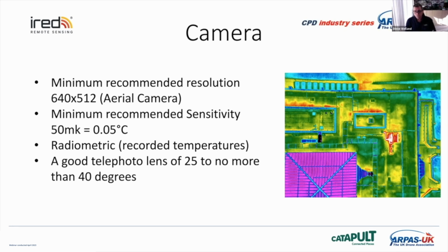All cameras really are required to be what we call radiometric cameras. Okay, and what a radiometric camera is, in its most simplest form, is a camera that captures that radiation leaving a surface as a CSV file or Excel spreadsheet or a grid of numbers. Once we have that grid of values, then all other changes can be applied in software afterwards.